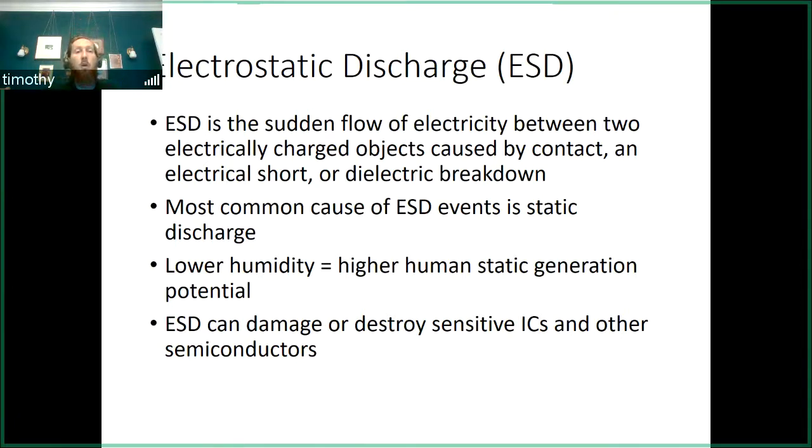If you're working from your home and you are working in a space that has carpet on the floor, that's a bad idea. Carpet generates tons of static. If you are working somewhere where it's carpet on the floor and then your desk does not have a ground mat, you are really not doing yourself any favors, and you could easily short out your electronics by ESD.